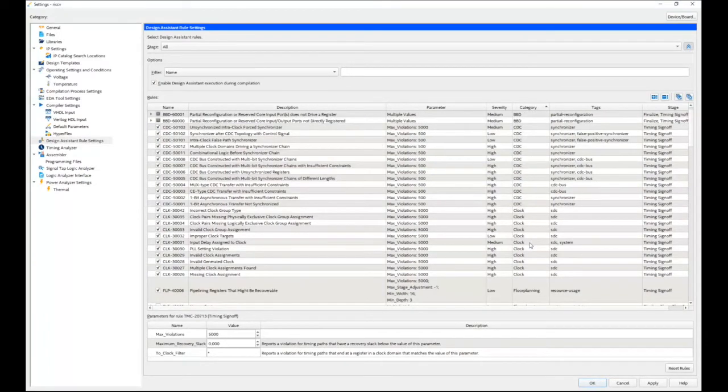Go ahead, Steve. We have a question in the chat, which is kind of related to this, but also goes into timing analysis. Is there an easy way to do analysis of different temperature or speed grades based on a given implementation result? For example, run an implementation based on a C7G speed grade and analyze timing behavior at C8G or I6G.